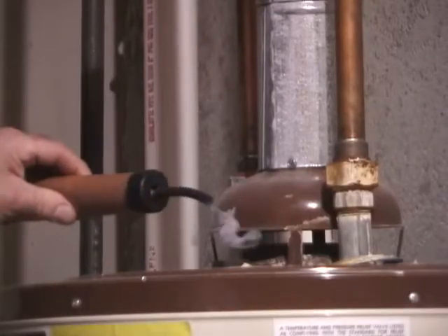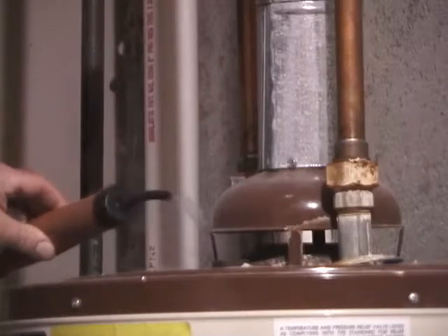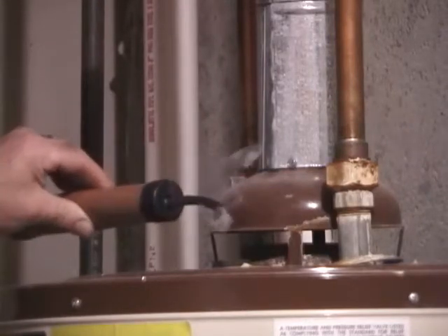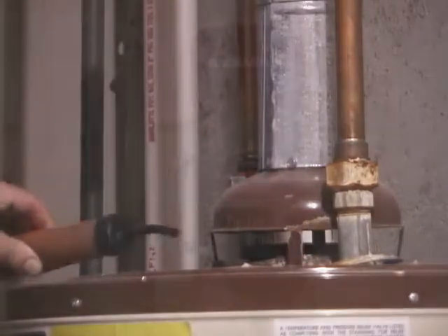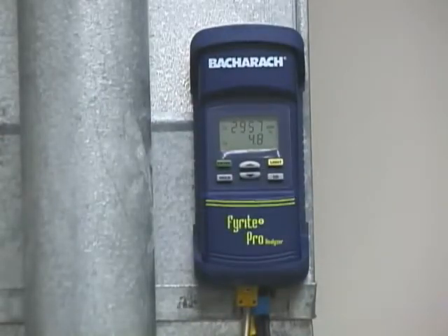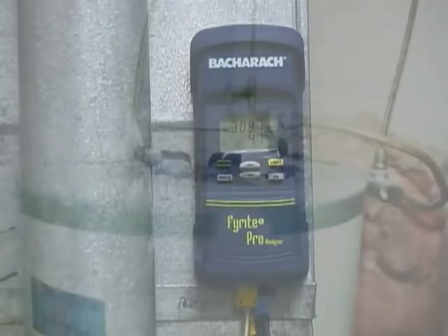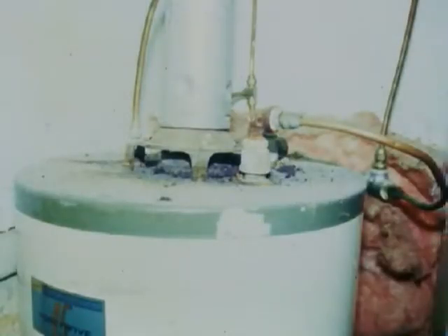In addition to spillage, backdrafting, or flame rollout, weak vent pressure can also affect carbon monoxide production because vent pressure dictates combustion air intake. The system can only draw in the same volume it can exhaust. If an appliance is not drafting properly, this can also negatively affect the combustion process, causing it to be incomplete and to create more dangerous combustion byproducts, specifically carbon monoxide.